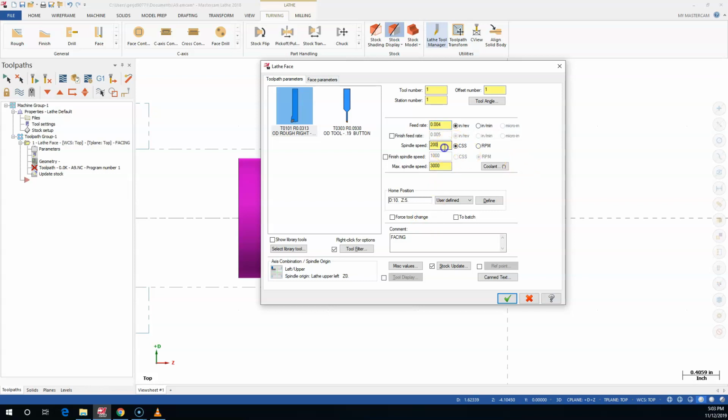I ought to be able to get this dialed in. And also, I'd have to go back and take a look at my tool settings. If I told it was from the tool, these tool settings just overrode what the control said. So we did keep our max spindle speed of 3,000, so I could build that into the machine. Wouldn't have that off, even if I had a 5,000 or 6,000 RPM spindle. I wouldn't have that off chance of, gee, it can go all the way up to 10,000.